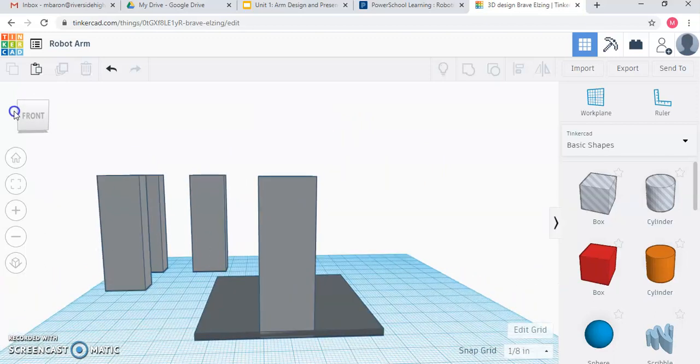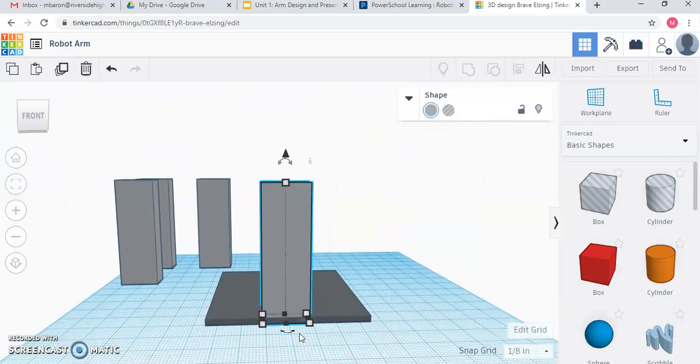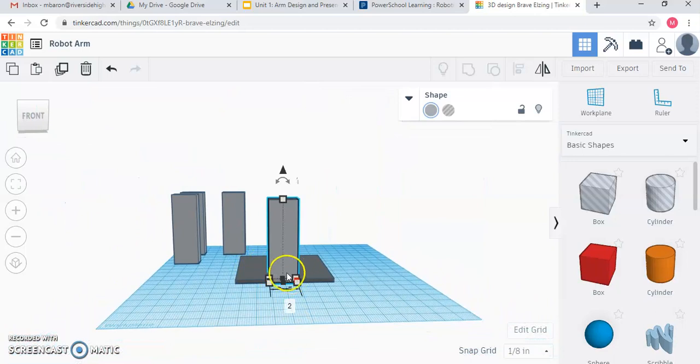You'll notice that this robot arm goes down, oops, into our drivetrain. Notice how there's this crossover in the 2 gray periods down here. We can't actually stick a C channel down into our drivetrain entirely. What we want it to do is to rest on top.